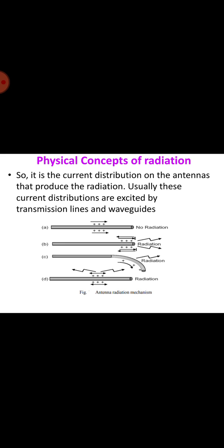In this sense, a receiving antenna may be regarded as a remote sensing temperature measuring device. So the radiation resistance RR may be thought of as a virtual resistance that doesn't exist physically, but as a quantity of the coupling of the antenna to distant regions of space via a virtual transmission line.